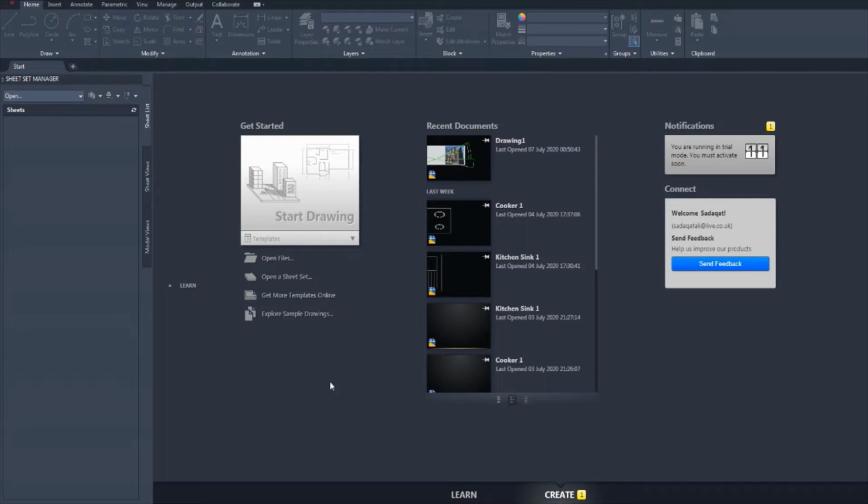In this series, we're using AutoCAD LT for architectural drawing, and our aim is to learn to use AutoCAD LT to create architectural documents like floor plans, building elevations, construction details, and more. Right now, we're building a library of drawings for all of the furniture items for the house. This is so that when we get to the stage where we draw our house plan, we can add our already drawn furniture into the project by inserting them into our plan. It saves us from having to draw them over and over again. All of the drawings that we're creating here follow the standard metric sizes so that we can insert them into any plan that we decide to create for the rest of our lives. And everything will be in proportion with everything else.